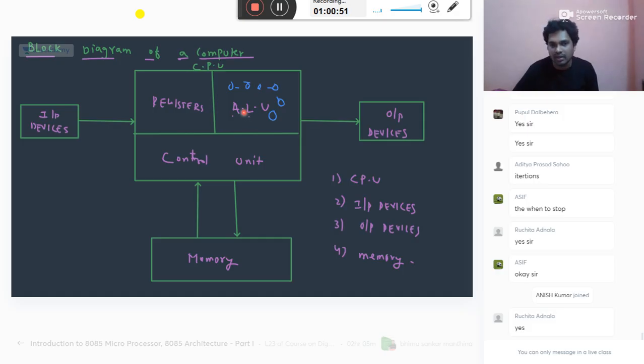in the ALU you will have different blocks, and we may use one or two blocks according to the instruction. When add comes, it should do the job of add only. When subtraction comes, it will activate the XOR gates and do the subtraction. That is done by whom? The control unit.